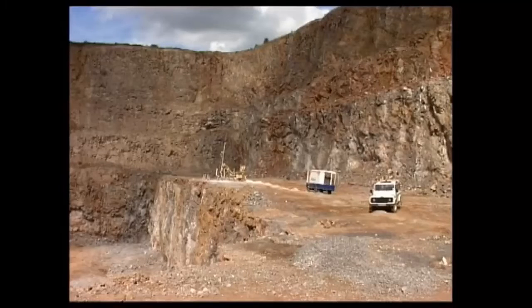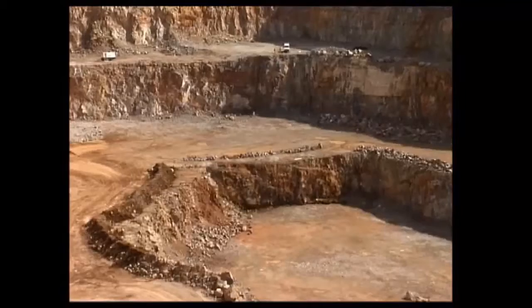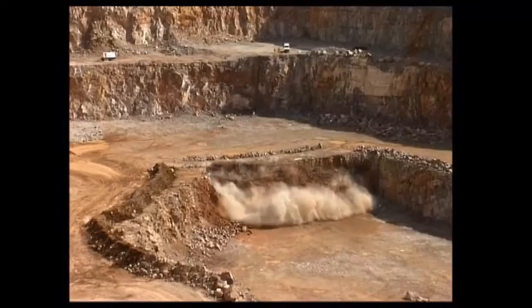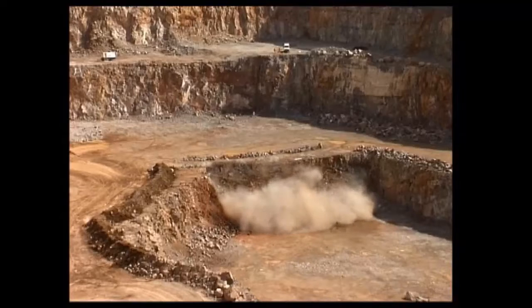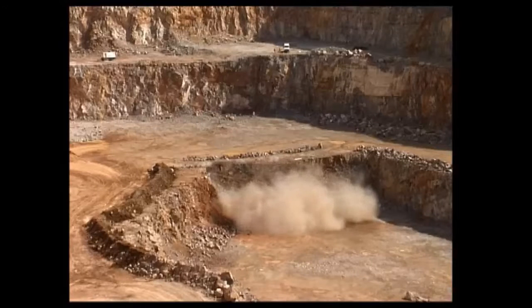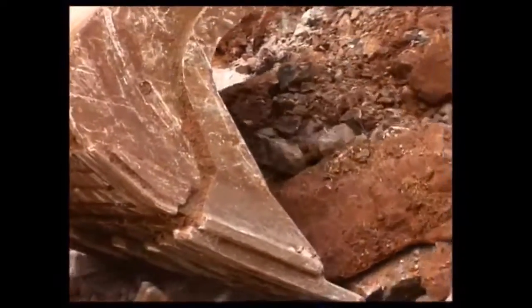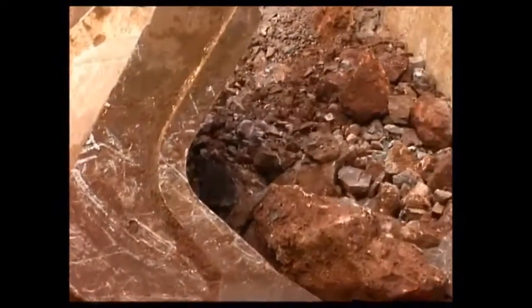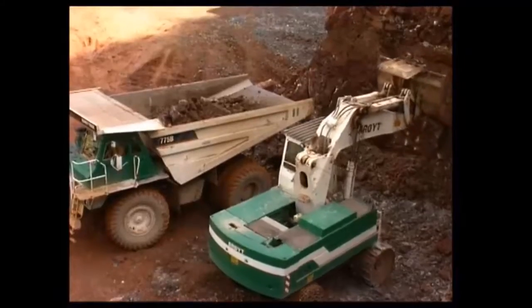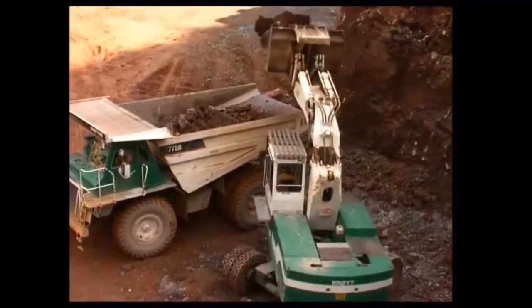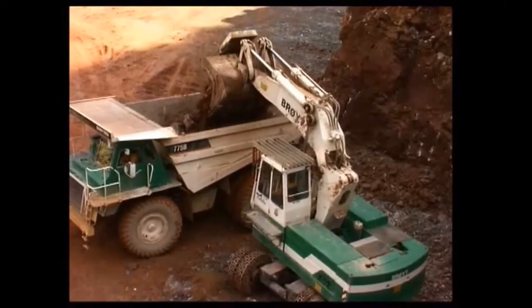The best hardcore is usually obtained from a quarry. This limestone quarry produces aggregates for concrete. The quarry waste is screened to remove loose earth and used for hardcore. Ideally, the stone should be graded. In other words, it should contain particles of different sizes. This helps compaction and minimises the risk of future settlement.